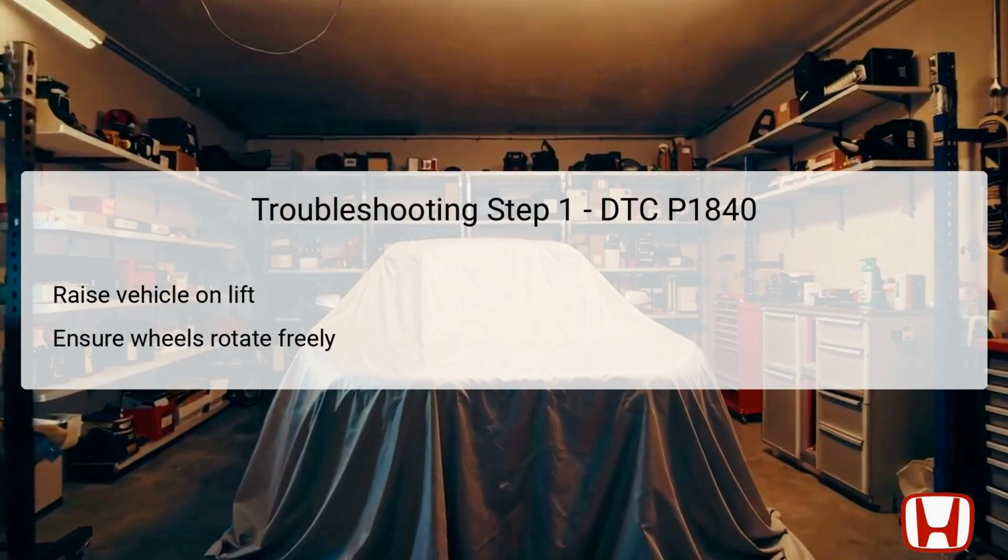In the second troubleshooting step, the engine of the vehicle must be started, and the Vehicle Stability Assist (VSA) system needs to be disabled. Disabling VSA is important because it allows the technician to evaluate the CVT system under normal operating conditions without external interference. The VSA helps maintain vehicle stability and traction, which is useful during dynamic driving conditions, but can affect the testing process.